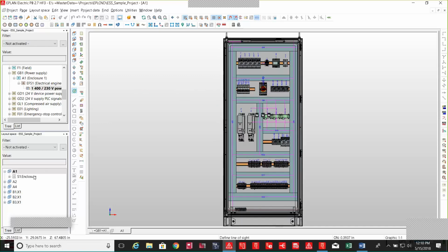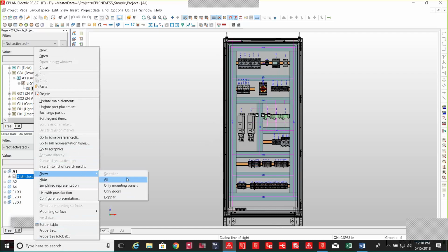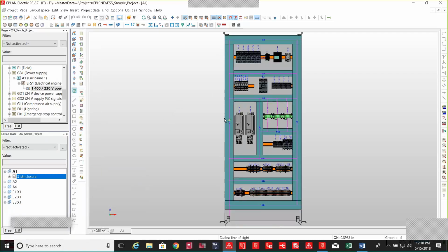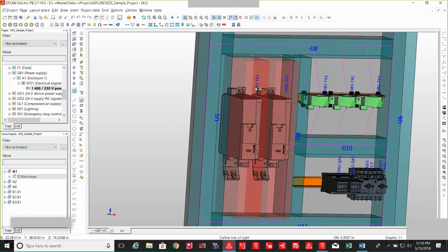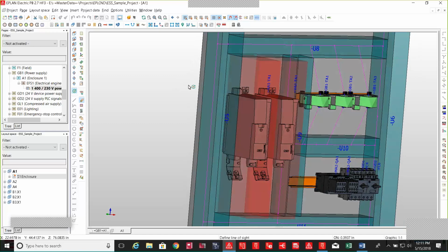If I look at the front view and I select the back plate, so I go here to mounting plate, all the objects and all the instances that I have here have been placed and associated, and I can start to have information relating to the components that I have here. I can activate some mounting clearance information, for components that, in this case, dissipate a lot of heat. Therefore, that information that's associated in my parts management for this particular component is displayed in an environment that is easy for me to see.